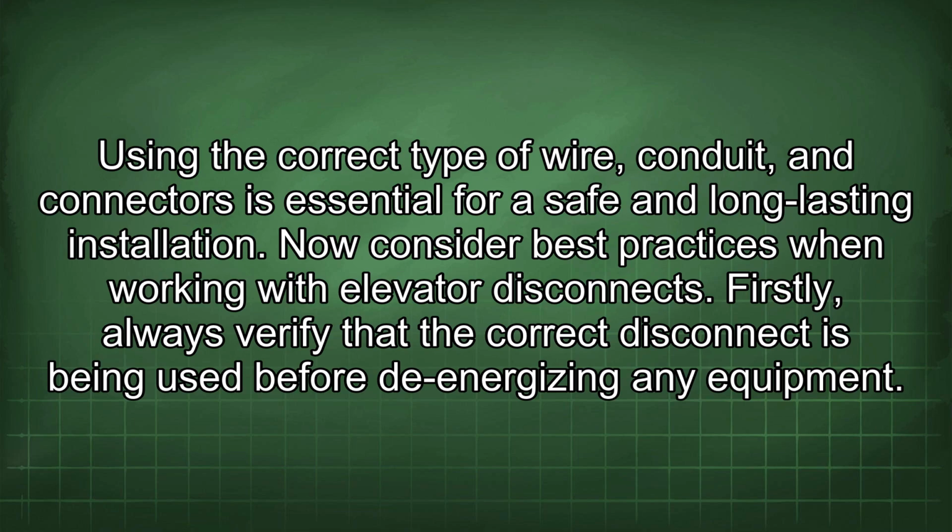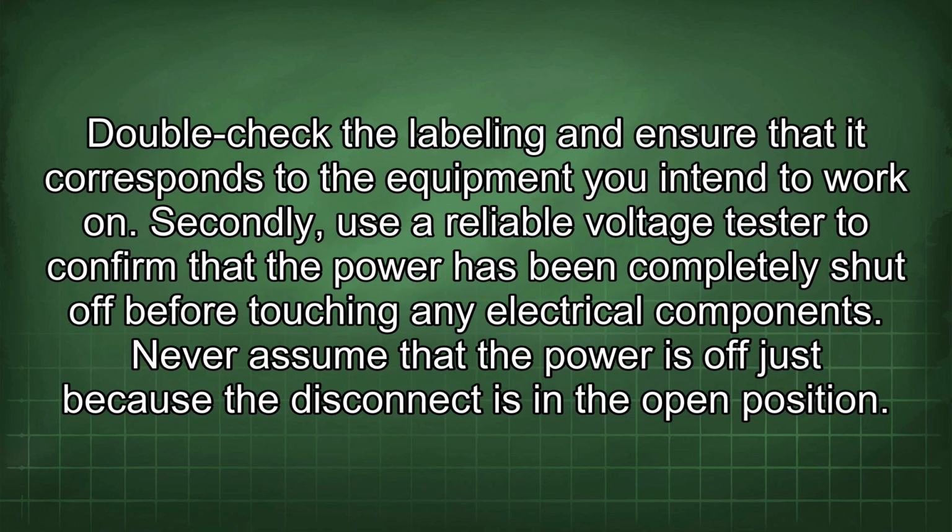Now consider best practices when working with elevator disconnects. Firstly, always verify that the correct disconnect is being used before de-energizing any equipment. Double-check the labeling and ensure that it corresponds to the equipment you intend to work on.